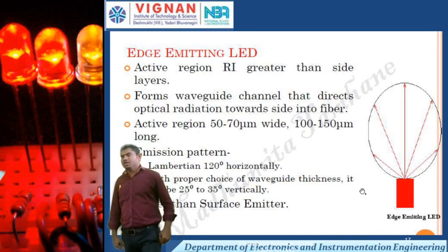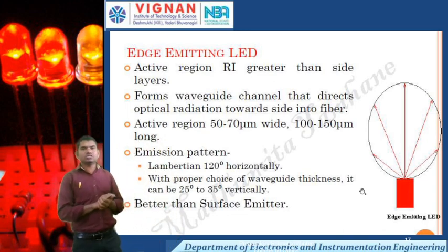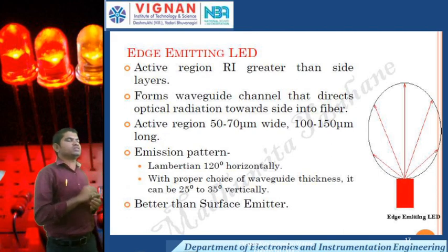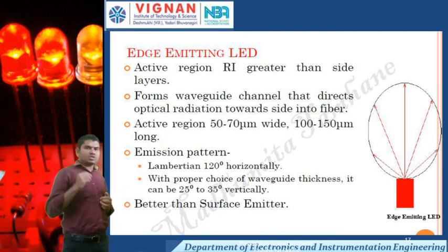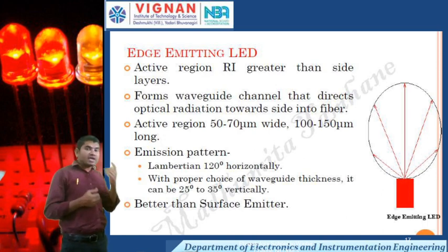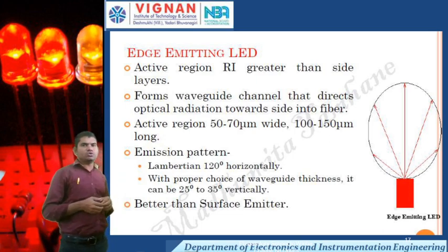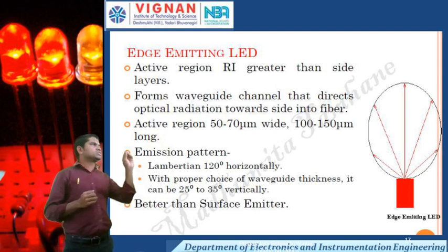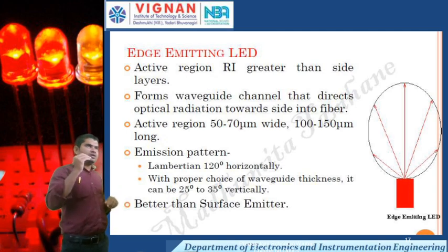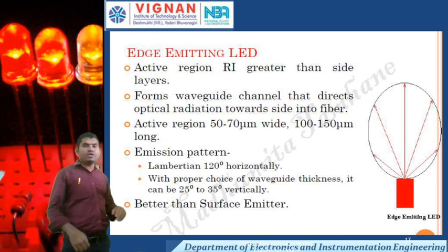In this edge emitting LED, the active region has a refractive index with gradient side layers, and it directs the optical radiation sideways into the fiber. The active region is 50 to 70 micrometers wide and 100 to 150 micrometers long.